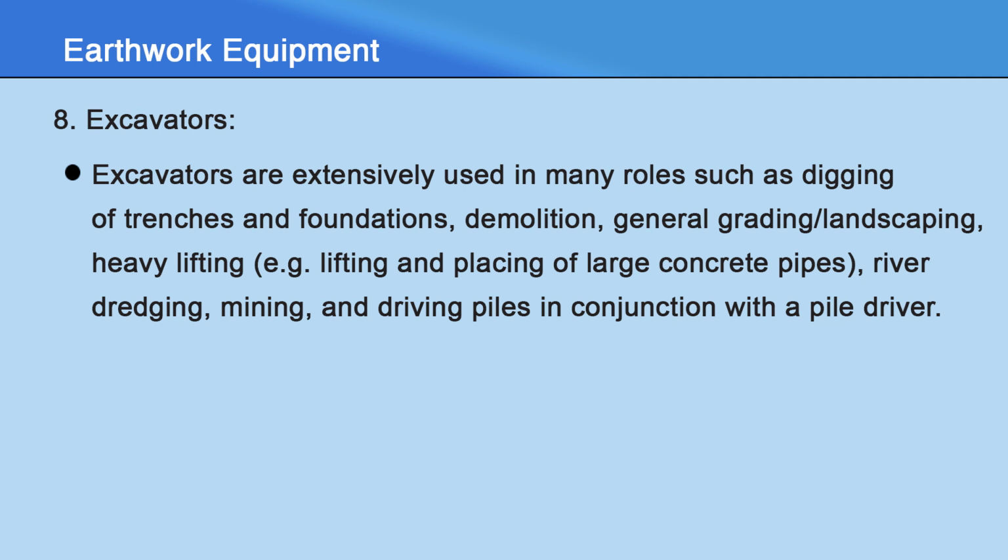Excavators. Excavators are extensively used in many roles such as digging of trenches and foundations, demolition, general grading or landscaping, heavy lifting, for example, lifting and placing of large concrete pipes, river dredging, mining, and driving piles in conjunction with a pile driver. They come in a range of capacities and are usually classified on the basis of tonnage. For earthwork, the most commonly used excavators are hydraulic excavators, which work with great efficiency.